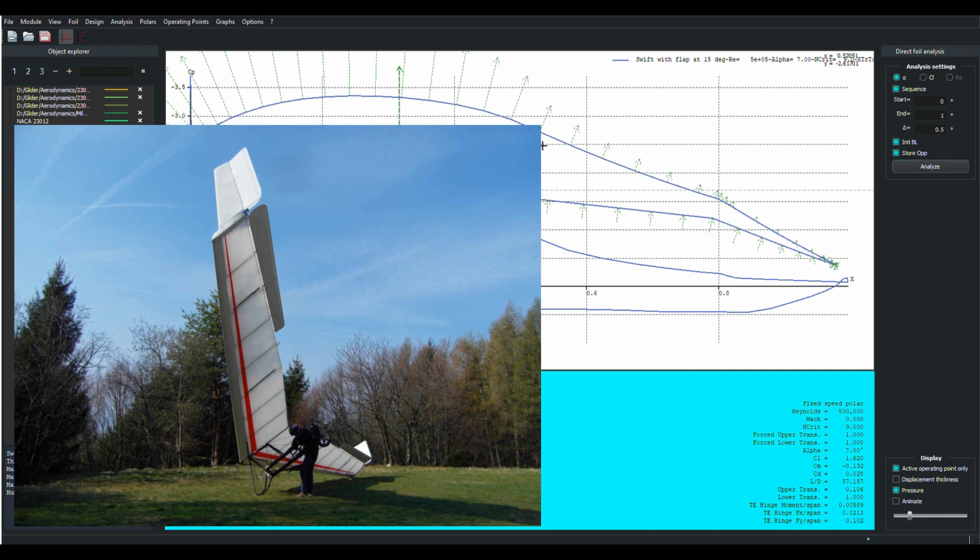He did it to reduce his induced drag by having the root end of the elevon have a smaller chord than the tip. And the way that it is integrated into the wing will very efficiently reduce the induced drag, which is exactly what you want to do for a flying wing. You want to get all of that induced drag as low as possible, and other drag. He's not peeling off a giant vortex at the root end of his elevon as if the elevon were just a big rectangular plate back there. You get a big rectangular plate, you get this giant vortex coming off the root end of the elevon every time you deflect it.